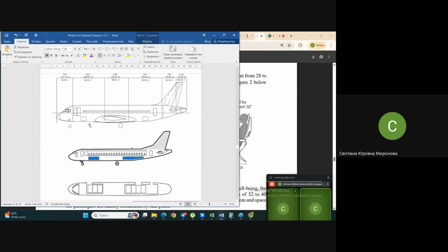And next, it's not even the thickness of structure between the interior skin and the outer skin. It would be no less than 15 centimeters, actually. Because there we have structural elements, electrical wires, some systems, and noise and heat protection materials inside, between the interior skin and outer skin.